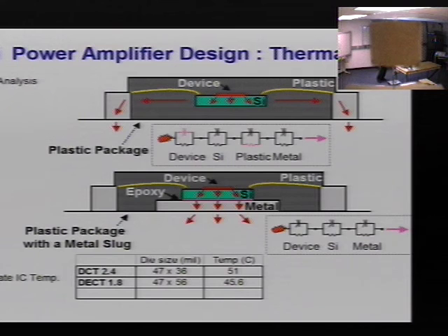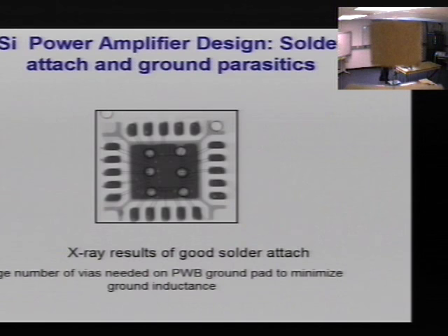But this was a steady state worst case situation, and it's a 25 rise already, so it's very worrisome at 85C, because you have to pass specs at 85C, which would put you at 110, and GSM would be somewhat similar. Well, GSM is a different story. I'll talk about that a little bit later.